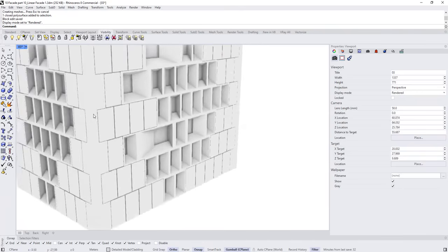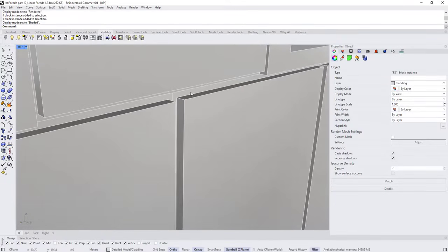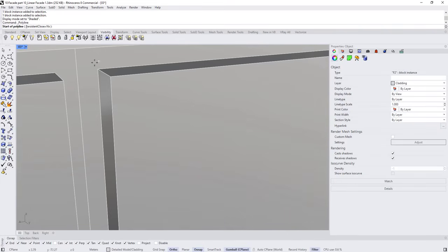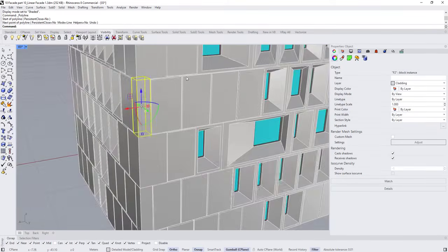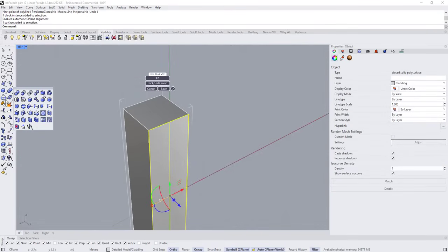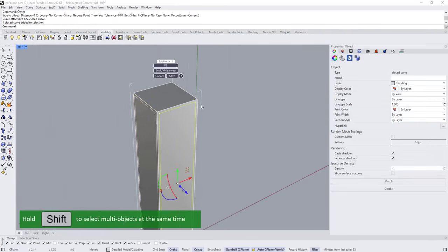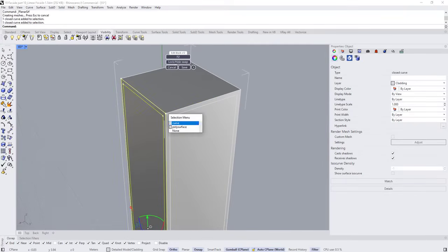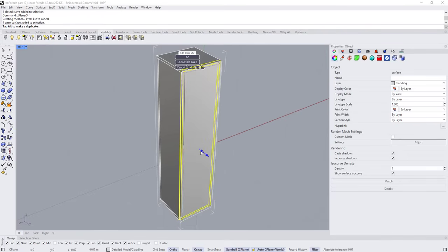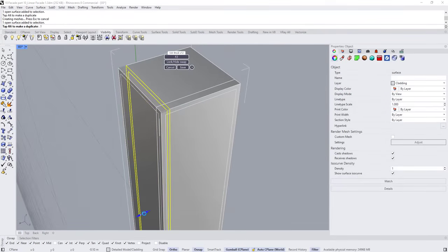Okay, now let's start adding materials. Okay, no, before adding material, for this part in the corner, I need to add a seam like this one too. I forgot the length of this one, so I'm going to measure it. It was 0.05. Double click, choose auto discipline, select this one. Double click the border and double click the border of this one too. Control Shift, select the curve, offset 0.05. This one also offset 0.05. Let's select these curves, surface, and extrude the surface by 0.1 maybe. And this surface extruded by 0.12.